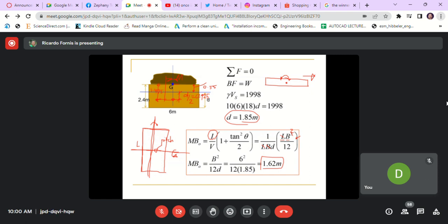But M is located at 1.62. So meaning, ang distance from G to M, that would be 0.145. So the metacentric height in this case is positive, no? Because you would say MBO, this is now the BO, minus GBO. Okay, so 0.145.